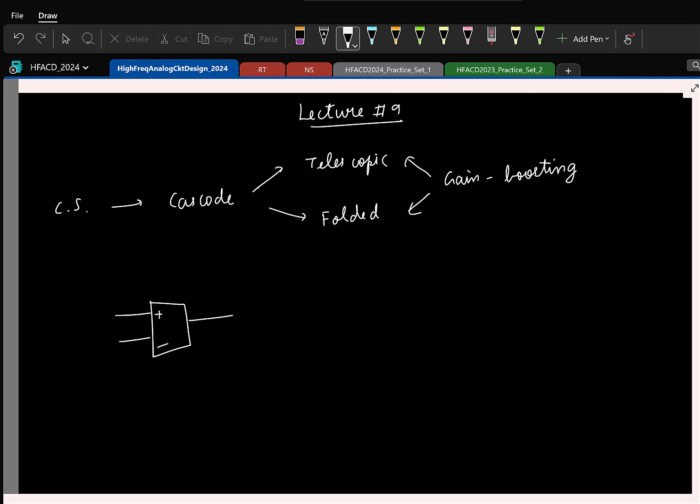So we have to deal with a whole bunch of stuff, and the most basic thing you'll have to deal with is the following, right? Let's say you want to measure the gain of this guy. You apply a small sinusoid and you measure how much it gets amplified, and you repeat this experiment by varying the frequency of the sinusoid. So what do you expect will happen to the magnitude of the gain? At least everyone is convinced that it will drop. And why is that so?